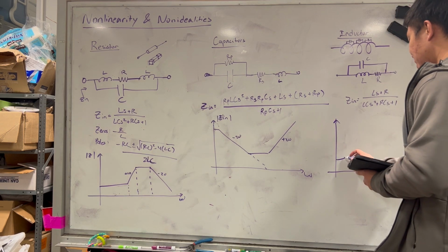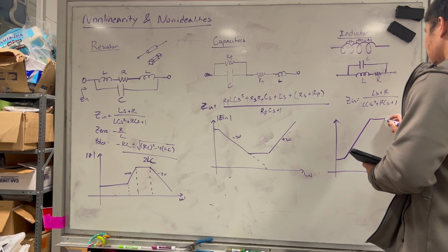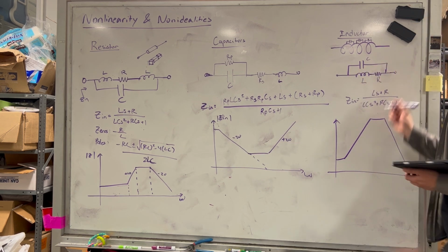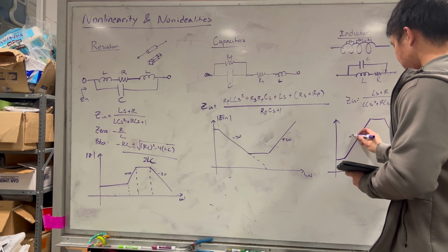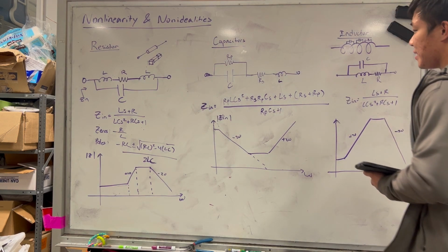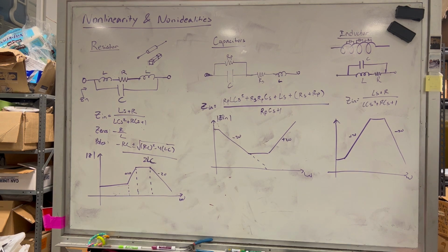But with that being said, that kind of gave away the answer. An inductor will also act like an inductor for only a certain amount of frequencies before the capacitance takes over, and you basically short out the inductor. So those are some of the effects of resistors, capacitors, inductors at higher and higher frequencies. Does anyone have any questions?